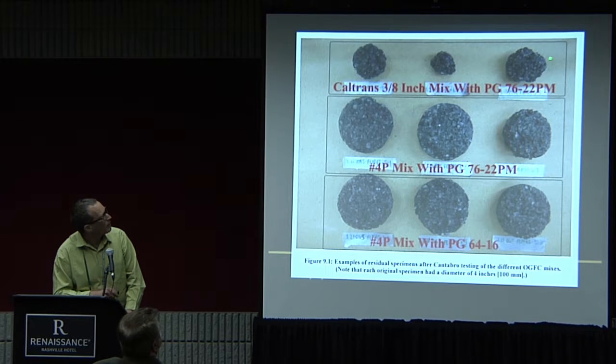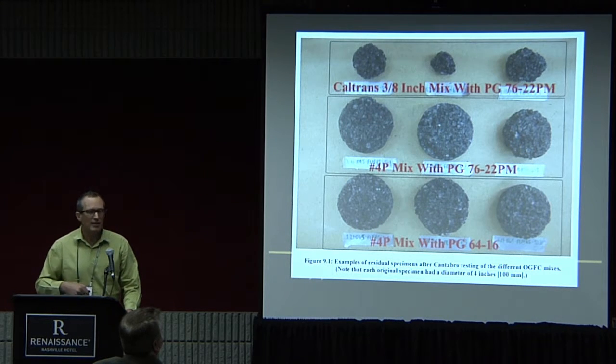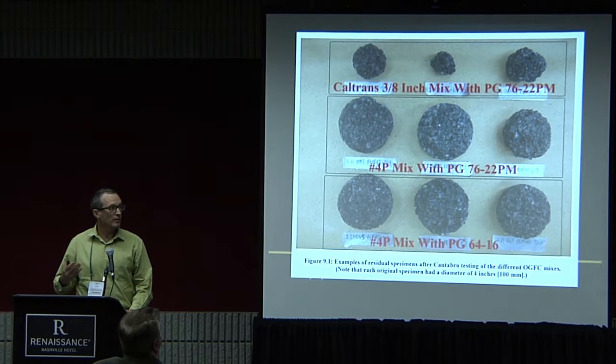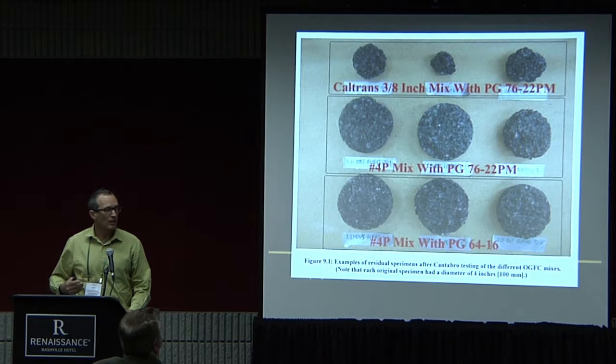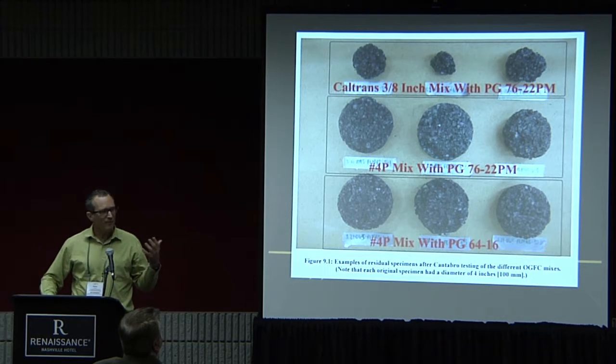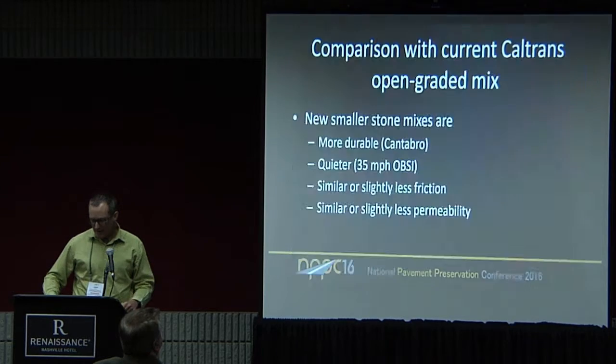So this is our current mix, and this is with a polymer modified binder. These are our smaller stone mix with the same polymer modified binder, and this is even with a conventional binder. So we think that these smaller stone mixes will also give us a greater raveling life over the long term. So we haven't found a downside to these yet.